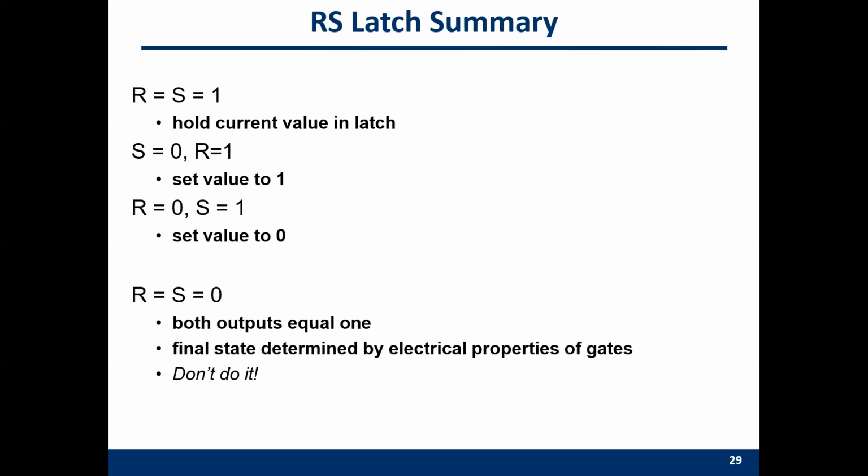For the SR latch, you can do the set, you can do the reset. You can also hold the value in the latch, but there is an unstable state. When you try to assign 0 to both S and R, you don't know the value of the SR latch.